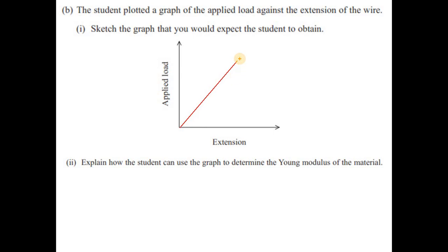Explain how the student can use the graph to determine the Young modulus of the material. Because the student is investigating the effect of load on the extension, from the graph the student is going to measure the gradient first. The gradient is load upon extension, so F upon delta L. This would be the gradient from the graph, and then you know that the Young modulus is